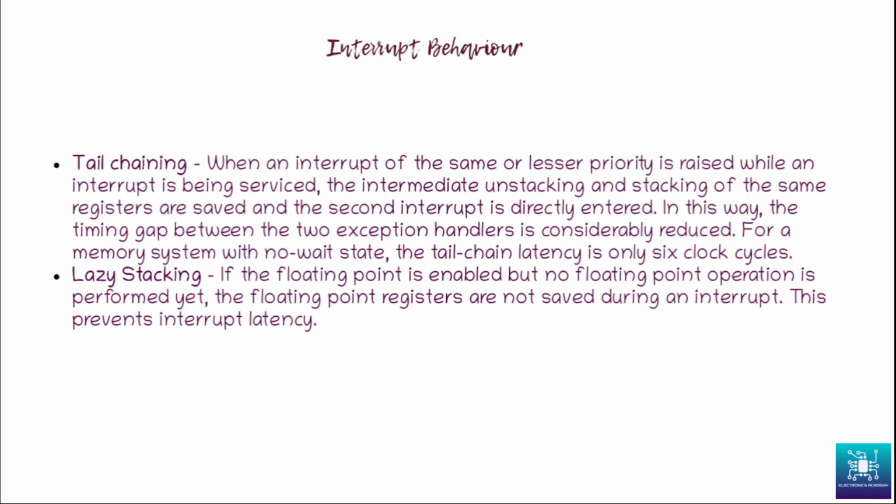And of course, stacking and unstacking is an expensive operation as far as latency is concerned. So what ARM Cortex does is it totally skips the stacking and the unstacking phase because it is not useful. It enters the second interrupt directly. In this case, for a memory system which has no wait state, the tail chain latency from one interrupt to the other is only 6 clock cycles, which is pretty good. So this is tail chaining.